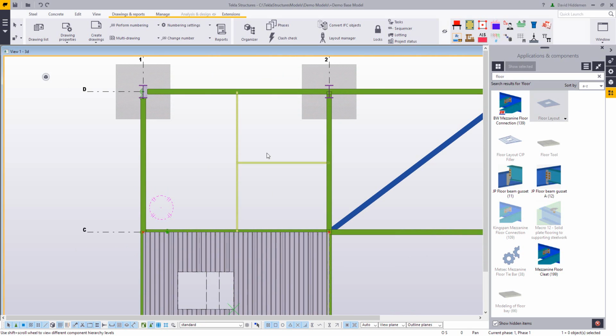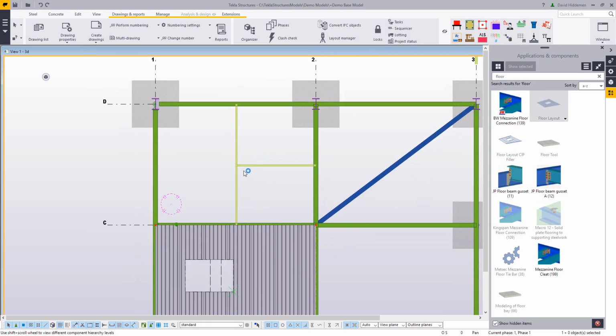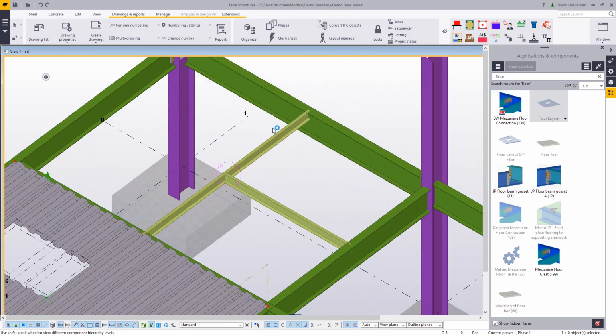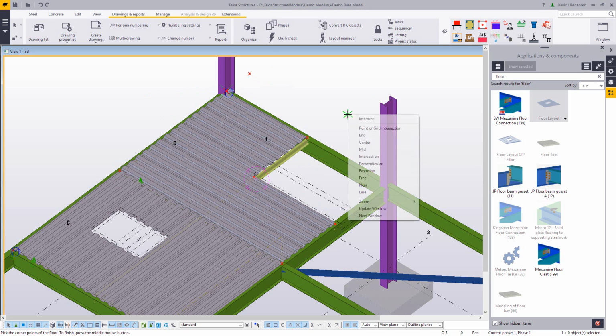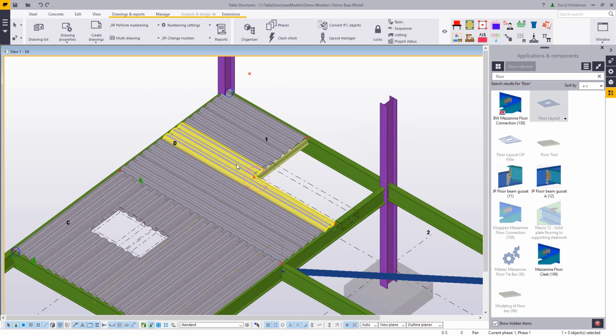So, let's say that we're doing a floor layout that's going to be an L shape. I'm going to leave this as an opening here. I can use those settings to simply pick around the edge of whatever I'm trying to clear or whatever needs to remain an opening. We'll close that off. And again, you can see how now it's adjusting the lengths and it's putting the cuts in for me automatically for parts that partially cover a hole.